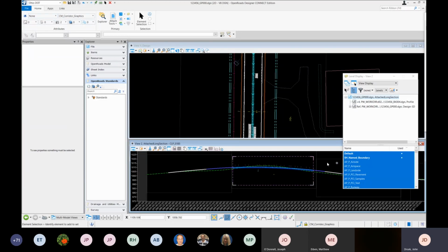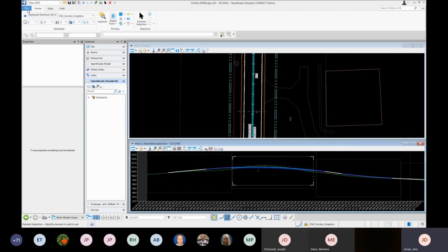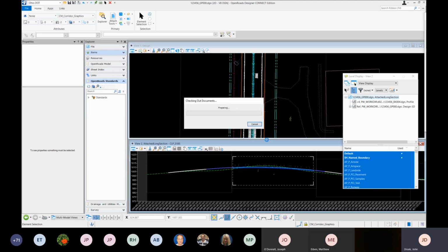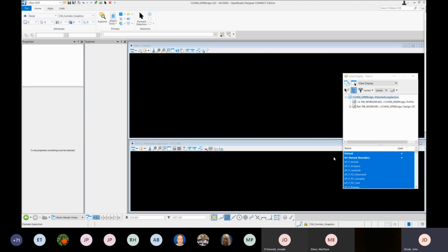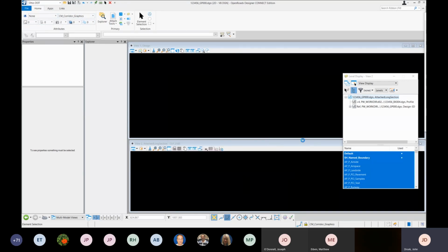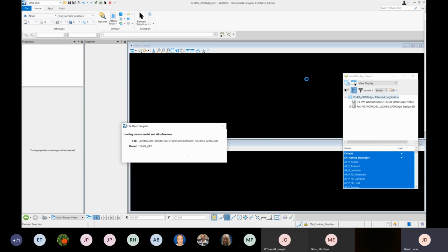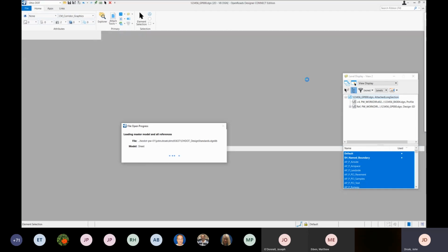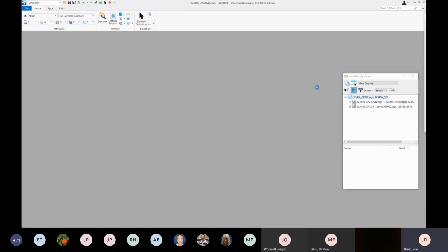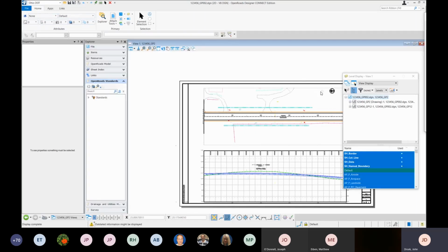So that was adding it. Let's go check out our sheet and make sure it does show up. So I'm going to switch files over to that GP file, the O2, because this is the second sheet. I'm going to check in this so it gets that 3D cut from the profile that we added and those new references. Okay, so it's loaded. I'm actually on sheet 2.